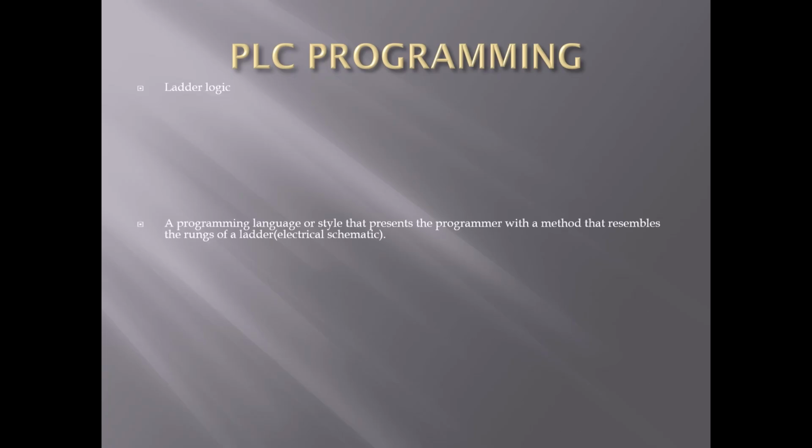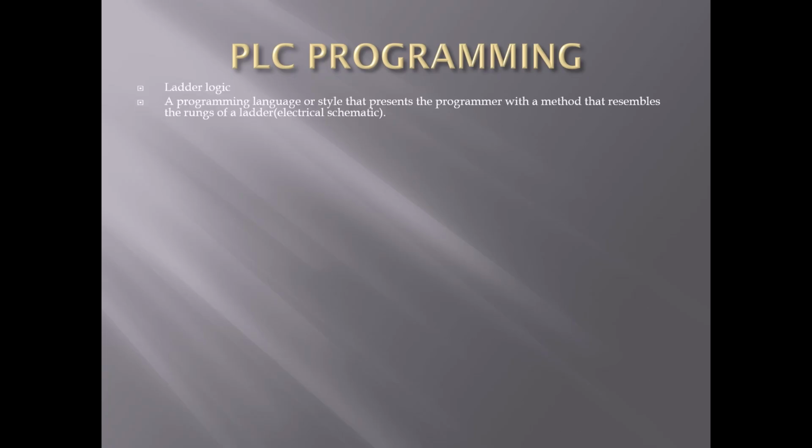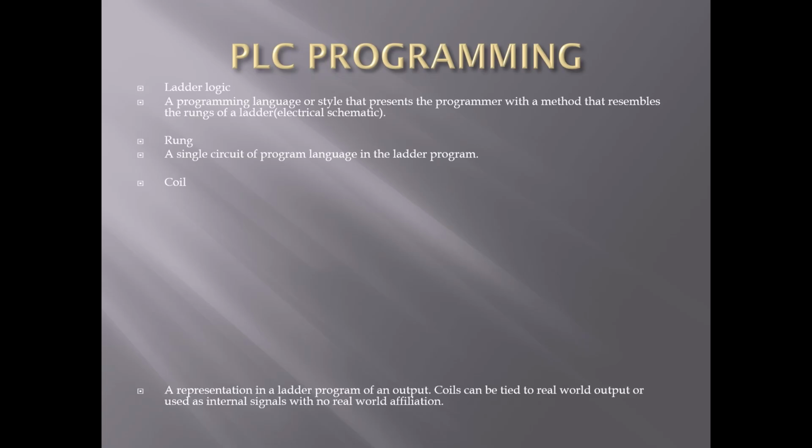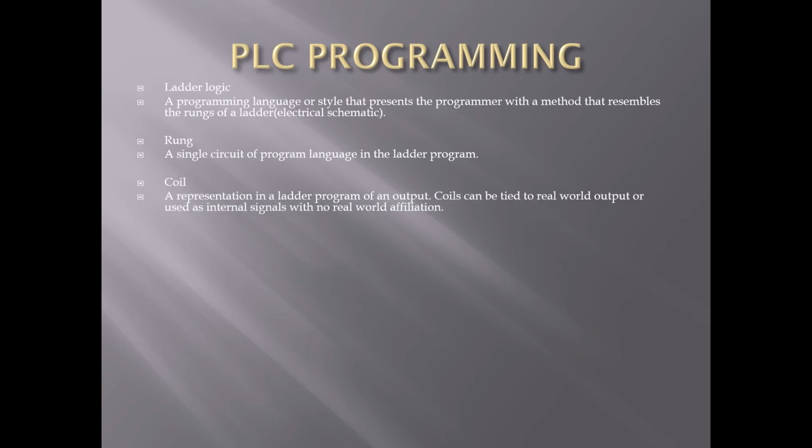Ladder logic. Ladder logic is a programming language or style that presents the programmer with a method that resembles the rungs of a ladder, i.e. electrical schematics. A rung is a single circuit of program language in the ladder program. Coil. A representation in the ladder program of an output. Coils can be used or tied to real-world outputs, or a coil can be an internal signal with no real-world